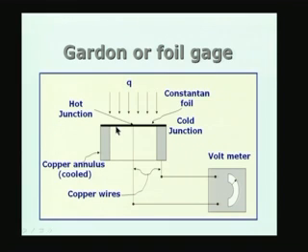So, what happens? We have a thin foil, and the heat transfer has to take place by conduction radially in the foil. So, the heat is received transversely, or perpendicular to the direction of the temperature field which is going to set up, and therefore, this corresponds to the case where the sensor temperature distribution is in a direction perpendicular to the direction of the heat flux.